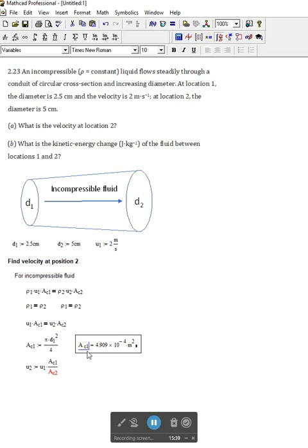Just click on the equal sign, and that is what MathCad uses to calculate and give me the value. And so you can see the different kinds of equal signs that MathCad uses. When I'm defining constants or defining variables with values, I use the shift colon. When I'm doing symbolic calculations, I use the control enter, because that enables me to then solve for these numbers, all right? And when I want to find and present the value, I just use the plain equal sign. And notice my units are SI base units, all right?